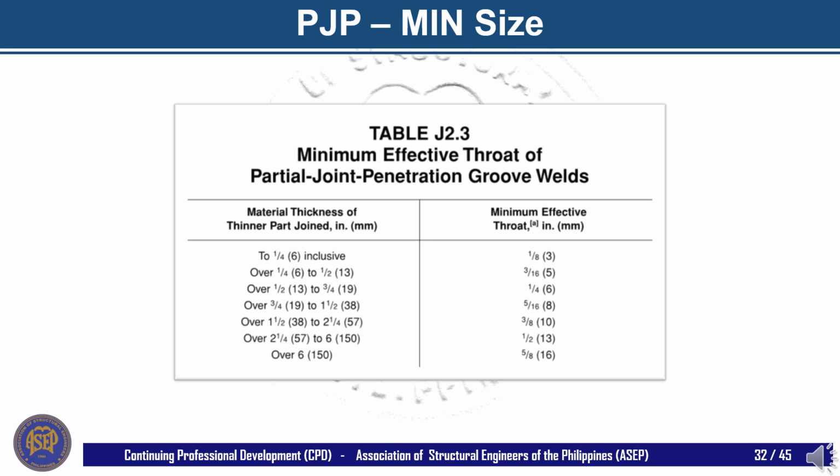As a result, performance of the connection is affected because the unfused plane may create a stress concentration depending on the loading direction. When loaded in shear, this stress concentration is of no concern. However, when the element is subjected to cyclic tensile loading, this region must be considered in the design of the connection.